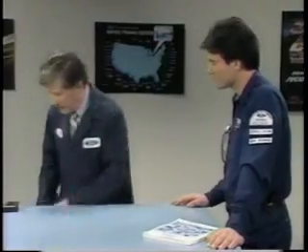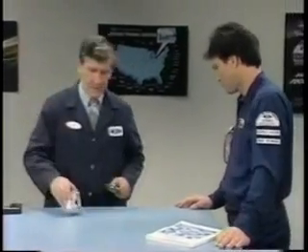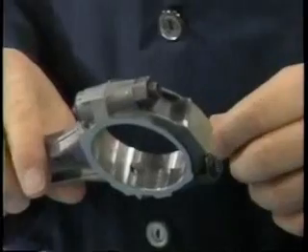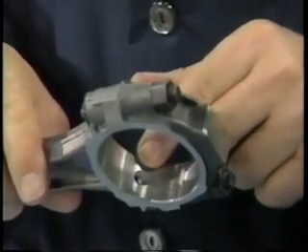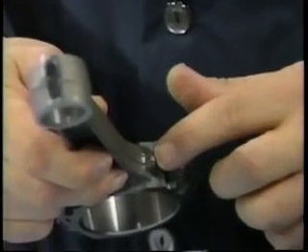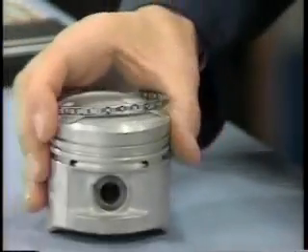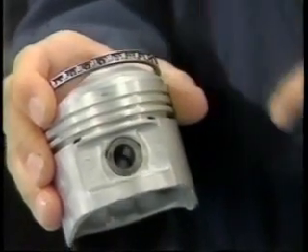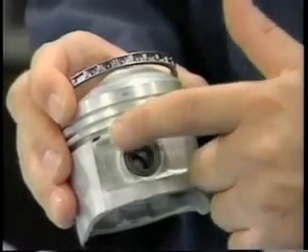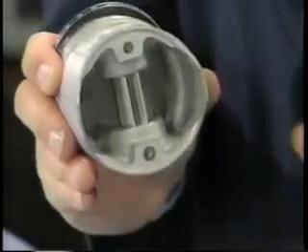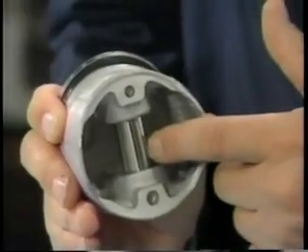In addition to the spray that typically comes off the bearings, some engines are designed to provide a more direct spray of oil to the cylinder wall through a squirt hole in the connecting rod, which provides a spray of oil under the cylinder wall as the engine runs. The excess oil on the cylinder wall is scraped off by the oil control ring and drains through these return holes cut in the piston ring groove. The splash of oil coming through the return holes is what lubricates the piston pin.